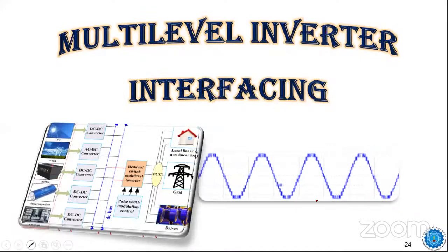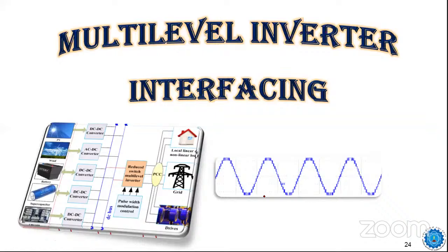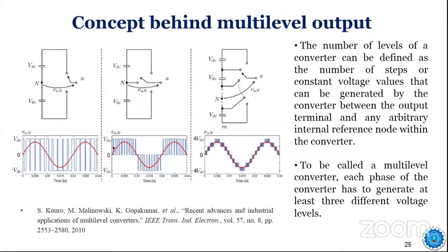So here, as you can see, the multi-level inverter plays a major role, as I was telling you already. What we are generally doing with the help of a multi-level inverter is developing the required staircase output. You see a 2-level inverter or a 3-level inverter. A 3-level inverter comes from the basic concept that we can develop a 0 level, right?